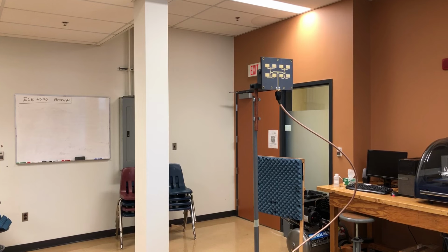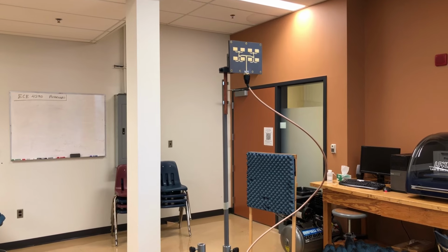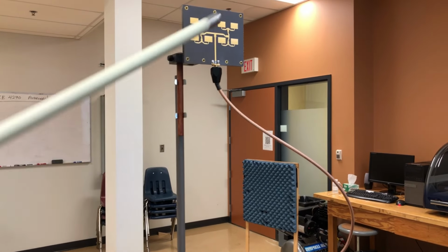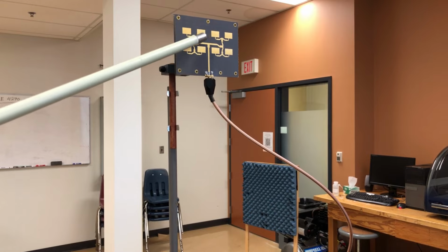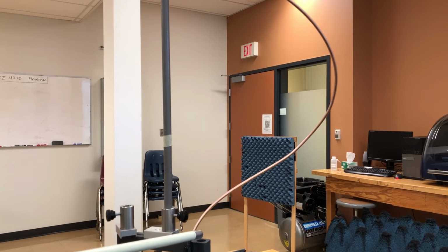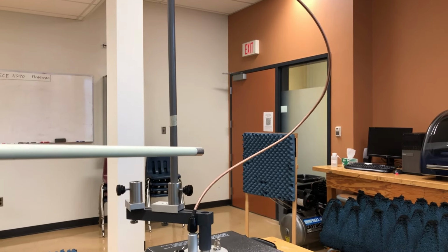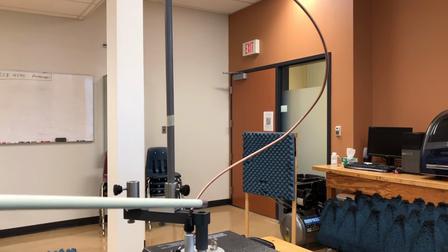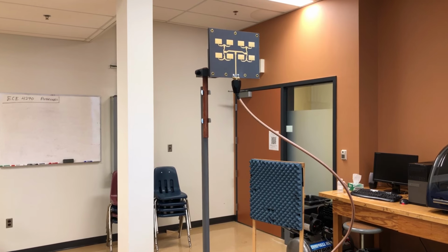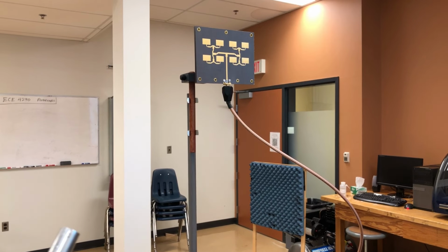Okay, we have our microstrip antenna array with parallel feed or corporate feed mounted. One thing to note here is that the center line of the antenna, which is this line over here, should be aligned with the axis of rotation. If you start from here and go up, that's your axis of rotation. This is the axis over which we are rotating. And of course the antenna right now is mounted in the H plane. Remember that the electric field of this antenna is now vertically polarized.